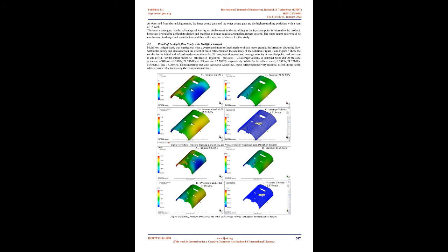Unlike in Moldflow where the CAD file was converted to a STEP file, Ansys 2020 R2 read the Creo 7.0 file directly. However, the gate at the chosen location had to be modeled in Creo prior to importation, whereas for the Moldflow study, modeling the gate involved a single click on the model within the Moldflow interface. An Ansys Workbench project was created with Fluent as the study.